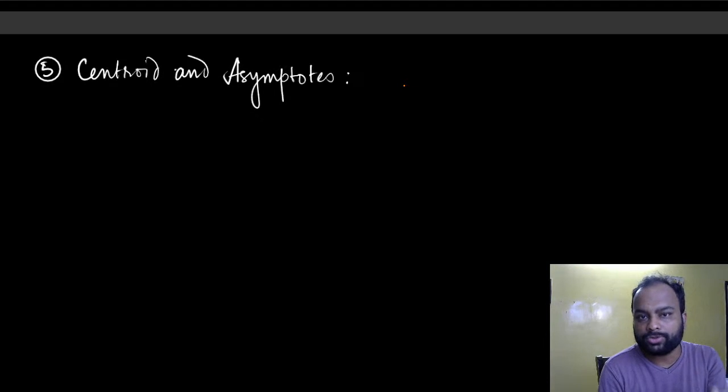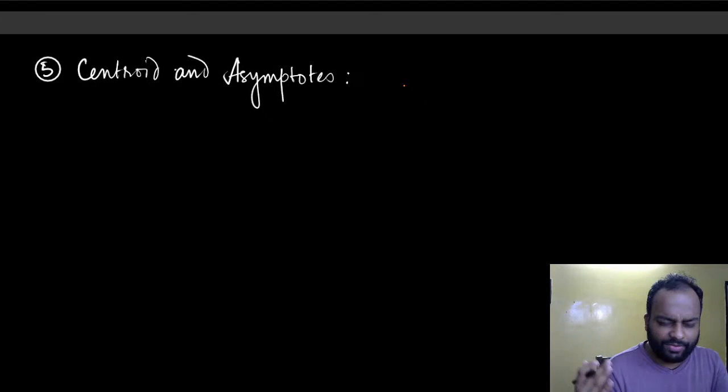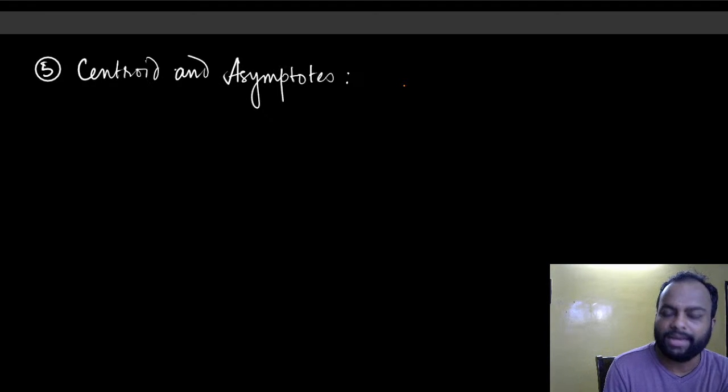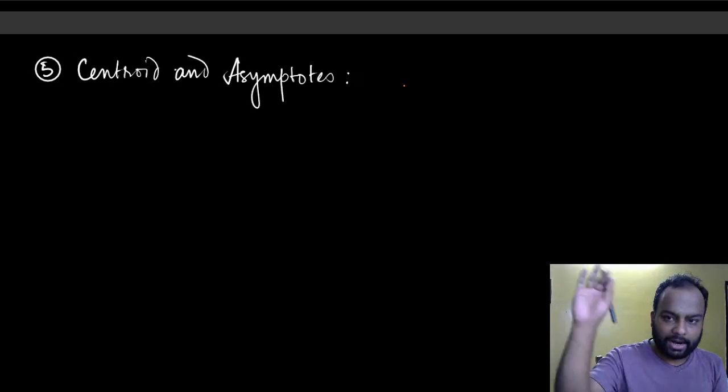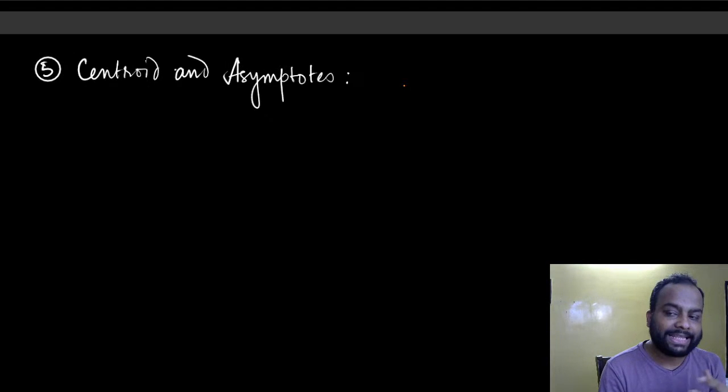What happens when the roots reach infinity? What happens when a very large gain appears? I'm saying that the roots go to infinity when the gain is infinite. So instead of arbitrarily drawing the curves when the gain goes to infinity, we are going to figure out certain things called asymptotes and draw the curves so that they follow the asymptotes, such that the asymptotes are tangents to those curves when the gain becomes infinity.